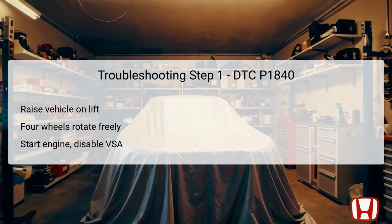The first step in troubleshooting DTC P1840 involves safely raising the vehicle on a lift. It's essential to ensure that the vehicle is securely supported to allow for safe inspection and testing of the components involved. Once elevated, check that all four wheels can rotate freely. This is crucial as any restrictions could potentially skew your test results.